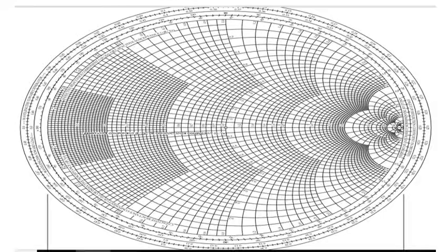Now to start with the problem, let us first plot the impedance point. So how do we plot the impedance point? The impedance given to us is 100 plus j80. So while solving it becomes 2 plus j1.6. So this is my 1, my unity gain circle. So 1, and then it becomes 1.2, 1.4, 1.6, 1.8. Yeah, this is my 2.